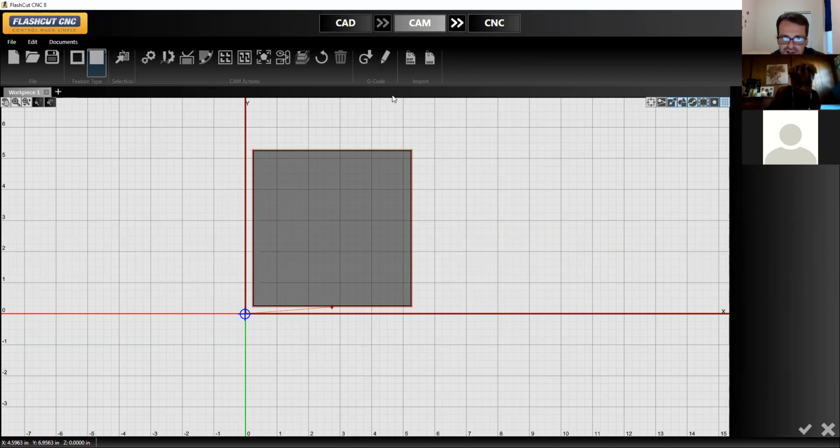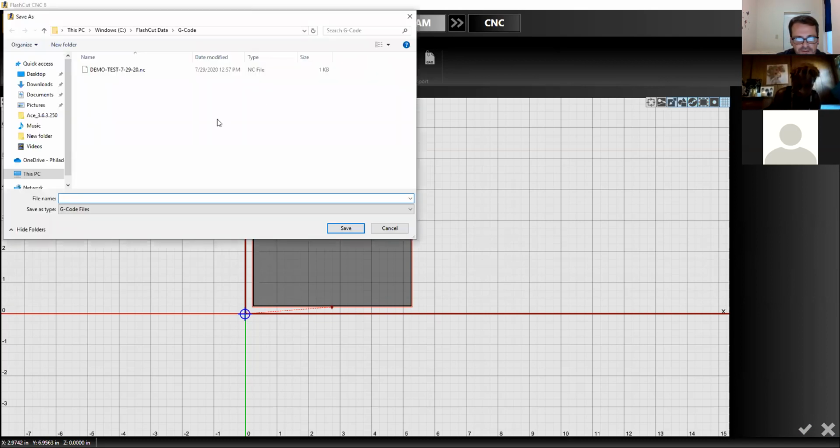Now, after we generate a G code, there's going to be another file generated. That's going to be a .cnc file, and I'll show you that now. We need to turn this into a series of code. That's how the machine will interpret this cut. So we go to create G code file, and G with the arrow. Click on that. Okay. And I'm just going to paste that file name in there. That way they're exactly the same.